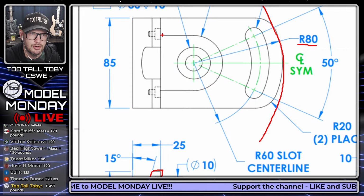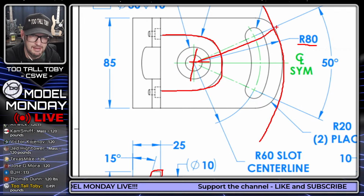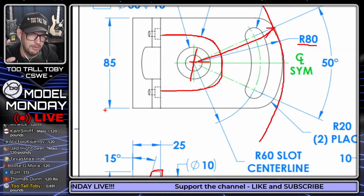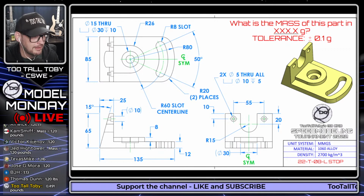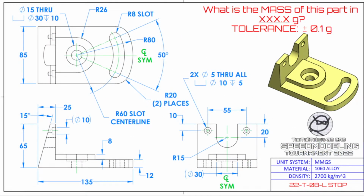That's just going to make it a little bit easier for me to visualize that design. And I might even create this tombstone shape first, so I can reference the center point of the tombstone shape for my radius 80. Sometimes thinking through these types of designs, whether you're speed modeling or designing in a professional environment, it's good to come up with a plan and understand how your different features are going to be related to one another. So that's how I would start out on a model like this. If you want to play along, feel free to grab a screen capture of this print and see how long it takes you to model.